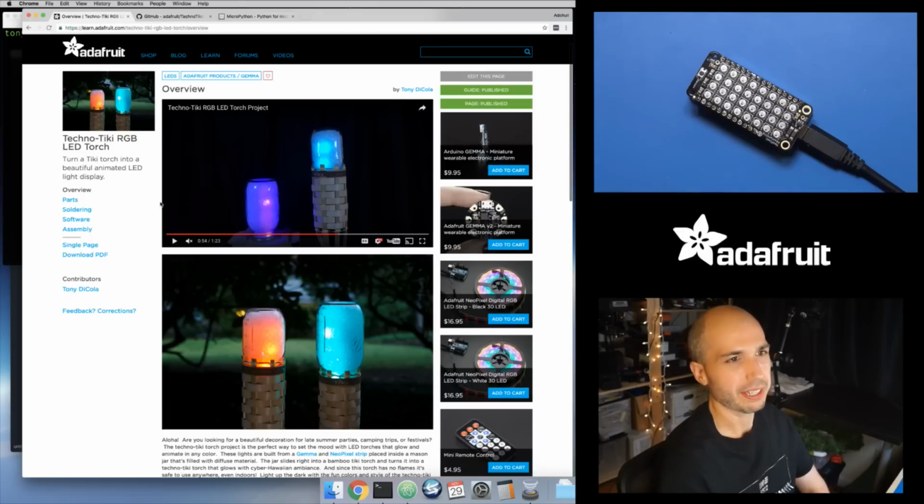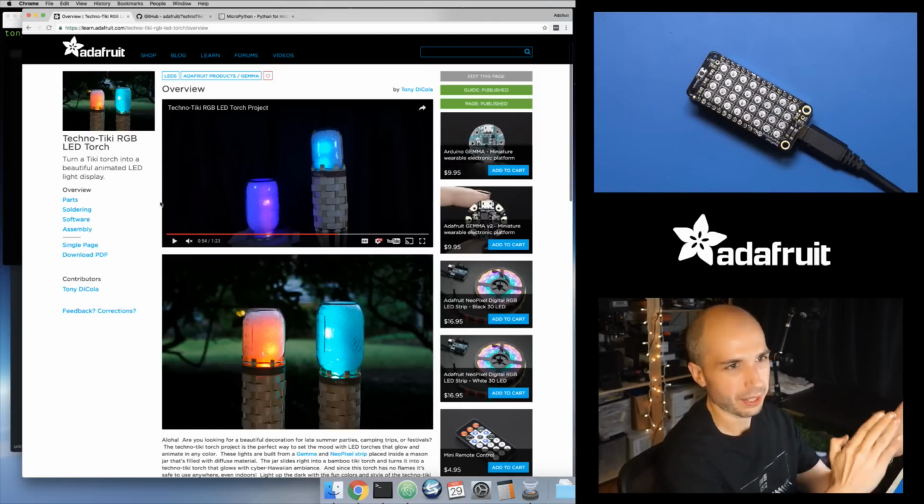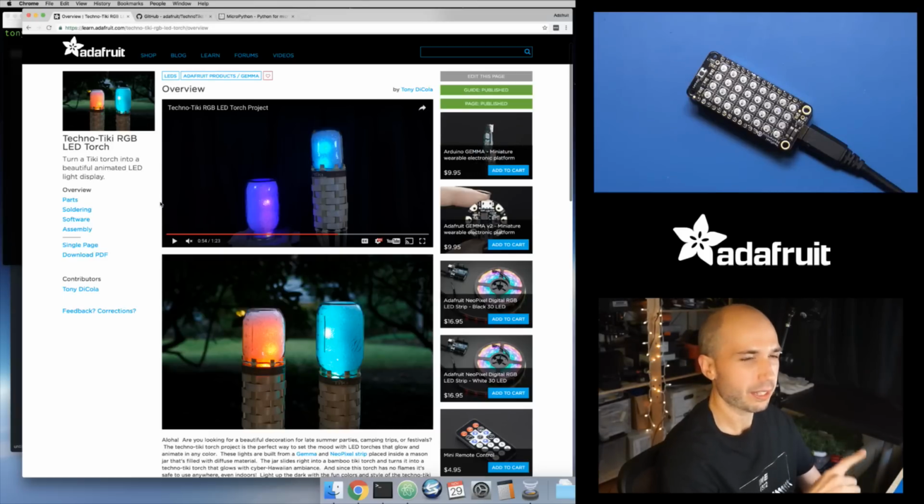And then I think I had a second type of animation where it would do like a theater chase, where the first pixel gets the first color, the second pixel gets the second color in the list, and so forth all the way through the list, and then it just moves that color set along all your pixels. So it looks like if you had 3 or 4 colors, it's just that set of colors moving along your line of pixels. It's a little bit easier once you see it to understand kind of what it means.